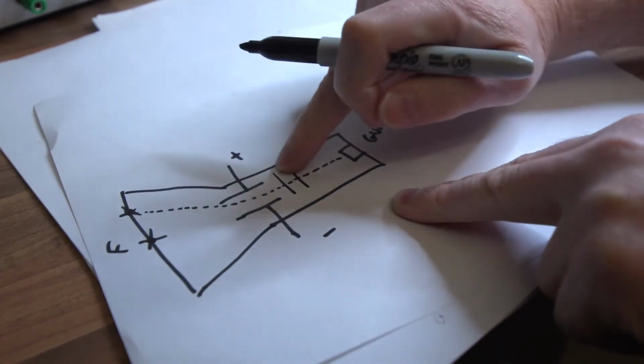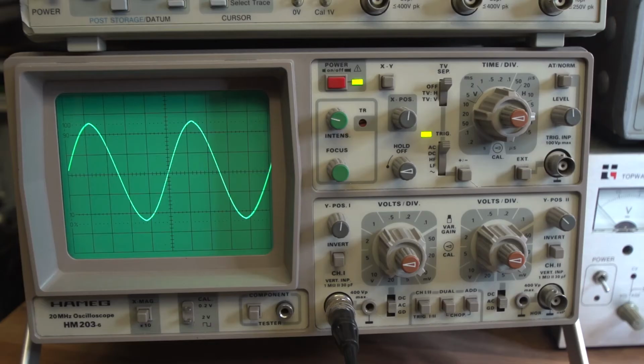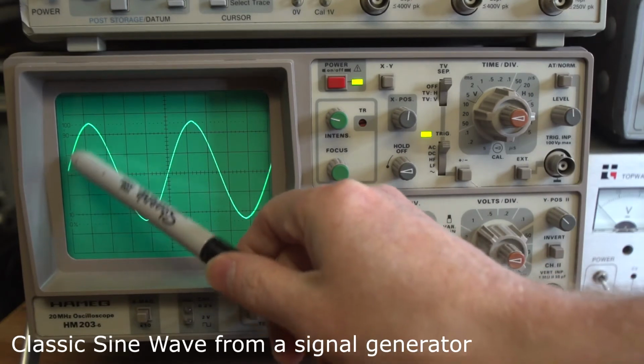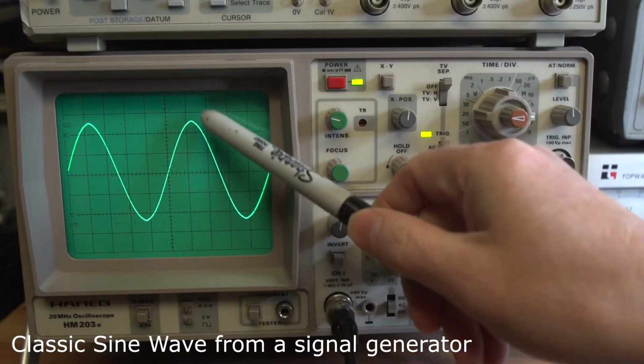So the X plates move the dot from left to right, which is your time base, or your X deflection. Now on the screen we've got what we call a sine wave, an equal amount of movement from positive, and then it slowly stops and goes negative, and then it stops at the bottom and goes positive again.